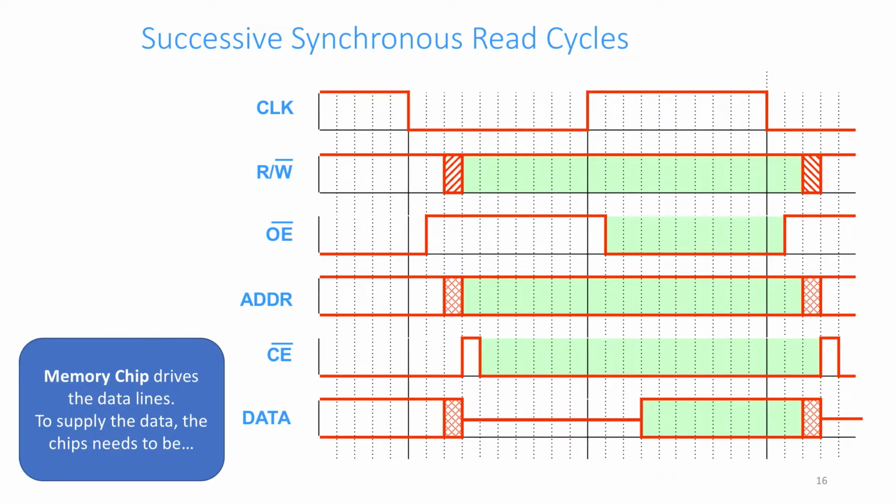We'll skip this. The next and most important piece here is the data line. This is a read operation, which means that the memory is going to be driving these data pins. The first bit of the data line is a result of the read from the previous cycle, and then the real read from memory that's happening on the cycle in question begins here. At this point, the memory is outputting the data on the data bus that the CPU wants, so it can potentially read it.